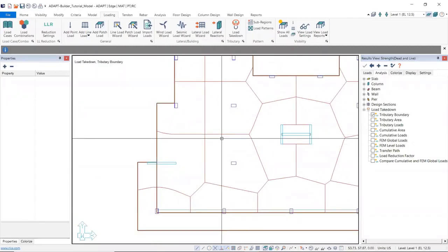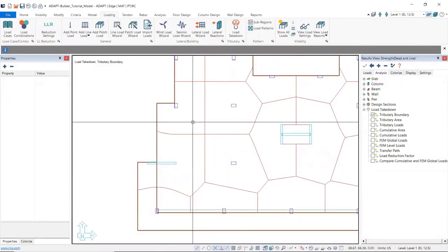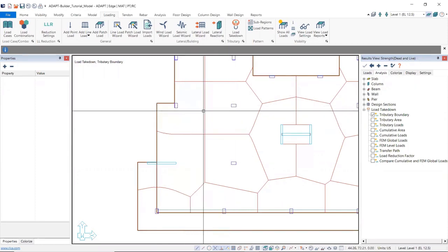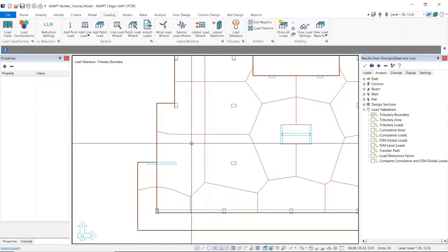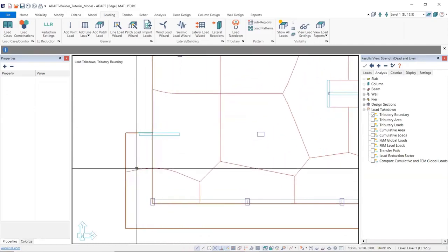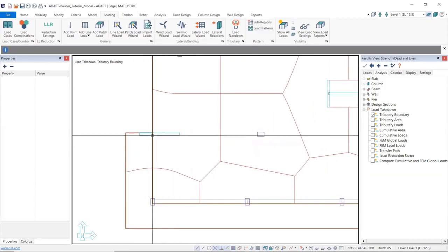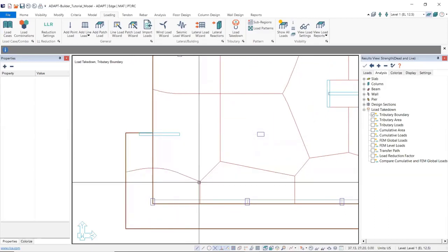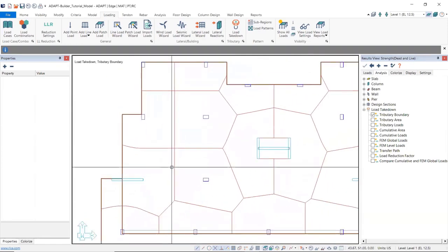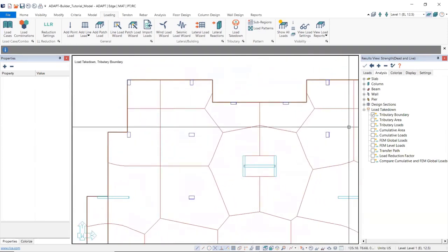And notice that this is similar to probably what you had done in college, where you're breaking out your ruler and you're measuring the distance between the columns and getting the tributary for it. But Builder is powerful in that it can determine the tributary based off of the entire length of this wall, which is resulting in this sweeping motion of this tributary area, which is really cool.